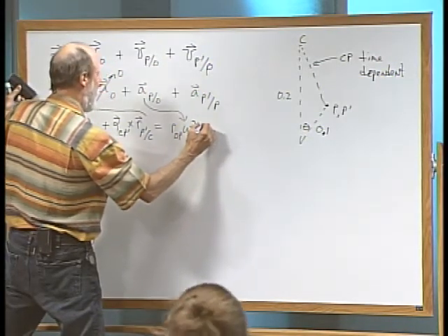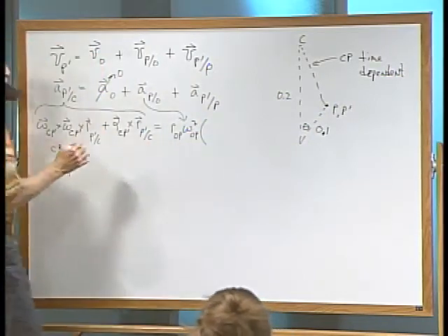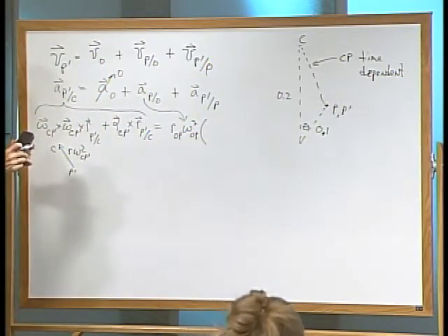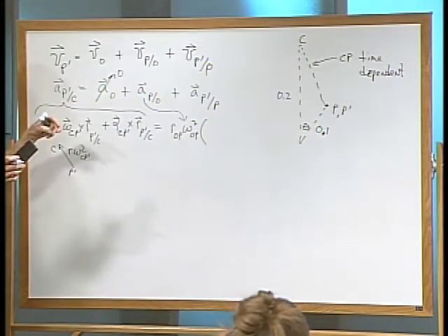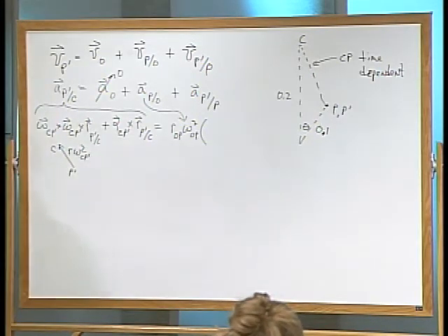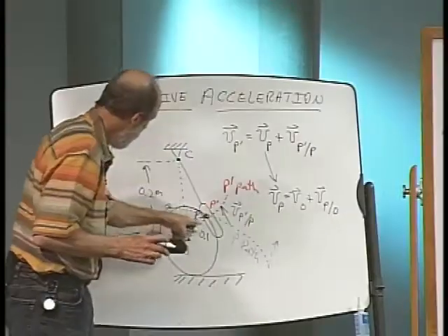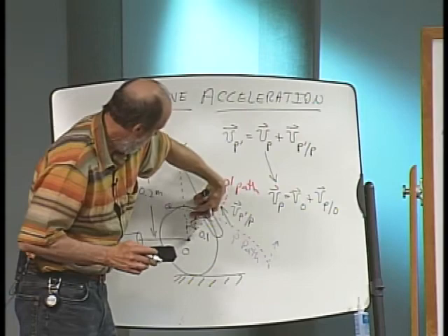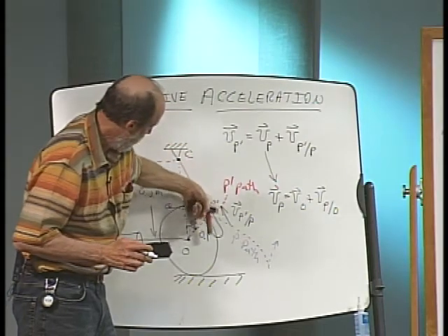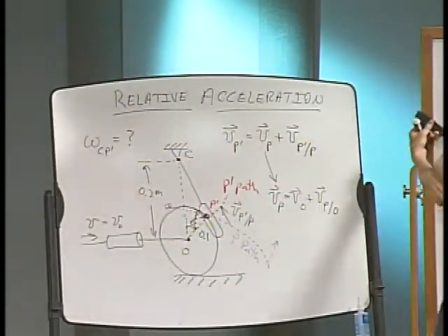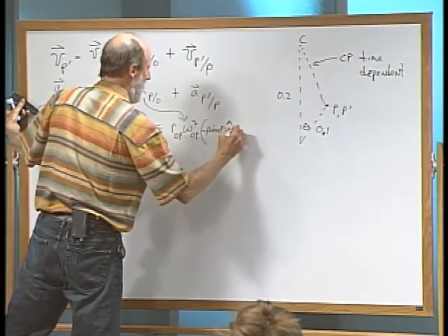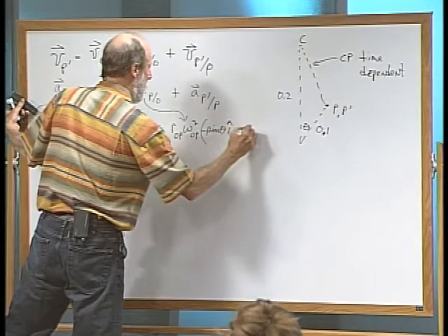And I'd make sure my direction was defined, pointing from P back towards O. So from P back towards O is going to have a minus sine theta term and a minus cosine theta term: minus sine theta i minus cos theta j.